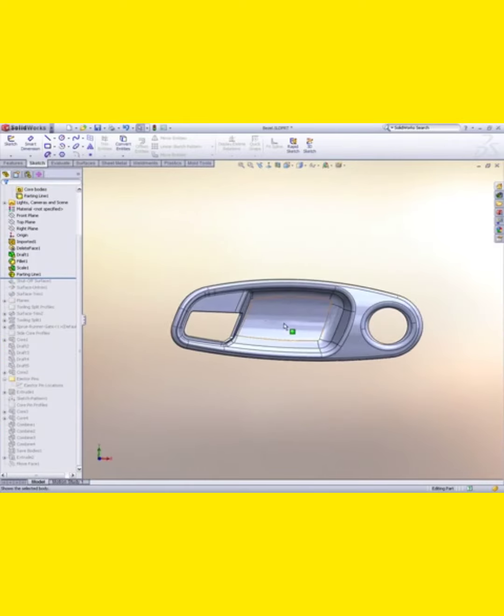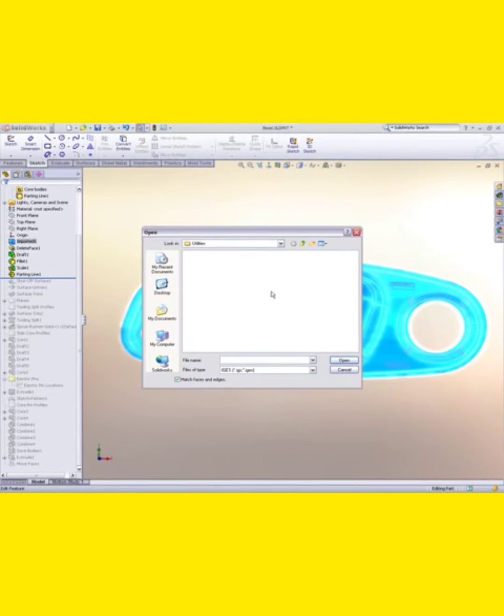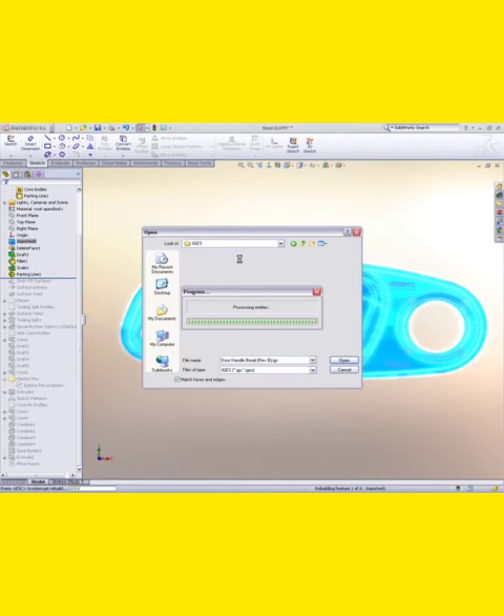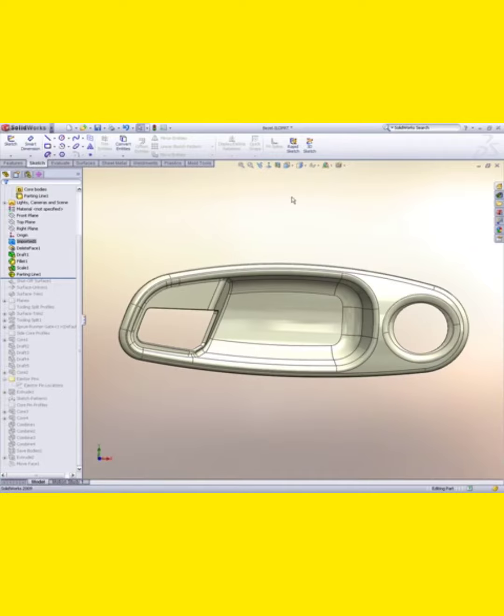Our existing design can be updated with the new IGES file, and everything will update automatically, providing the important edges and faces in the new file can be matched with the old. If a change conflicts with the previous design and requires a new parting surface or side core, SOLIDWORKS will indicate any potential errors and try its best to rebuild the mold. Problem areas can then be fixed manually until the mold is working as expected. The good news is that you won't have to start from scratch, even with the toughest of design changes. This change in geometry does not affect the split line or the